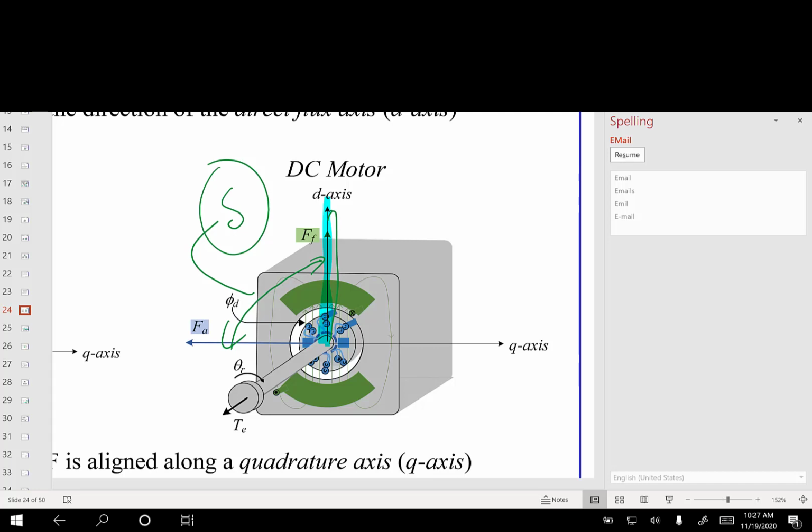They would make this big magnet and try to produce some kind of force and torque on the shaft, moving it while keeping these guys lined up. That's my idea: wherever the field is, what the field's doing, the armature displacement from the field is what makes your torque, and it's a fixed angle. So if the field's moving, the armature has to move. If the field's not moving, the armature has to not move. And that enables you to keep this angle fixed, and that angle defines the torque.